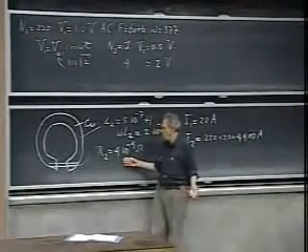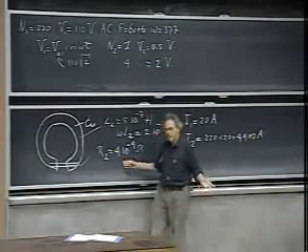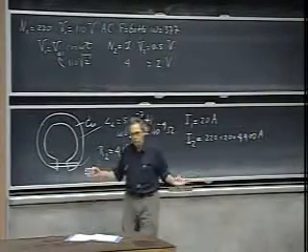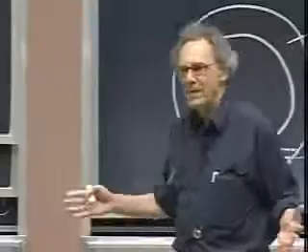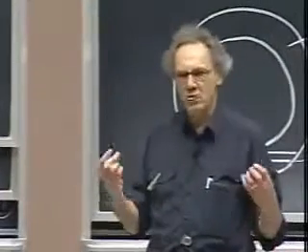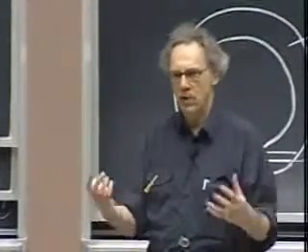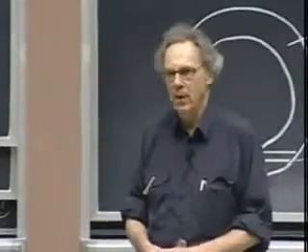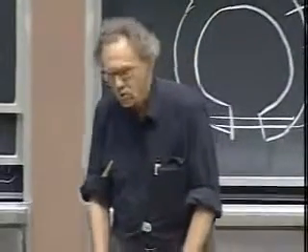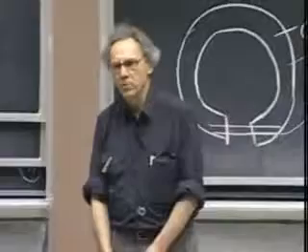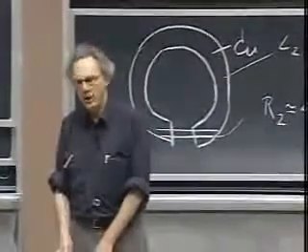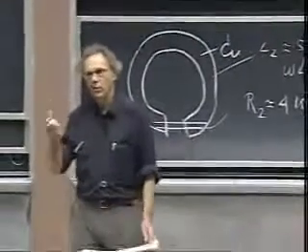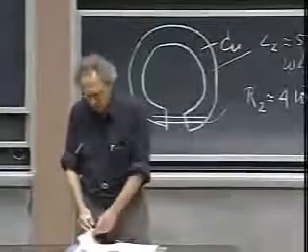And if my current, I2, becomes 500 to 1,000 amperes, you can calculate what I squared R2 is. Because you know R2, that's all in that nail. And that comes out to be about 100 to 400 watts. You better believe it that that nail is going to be red hot, is going to glow, and probably melt. And this is the idea behind so-called induction ovens. This is purposely done to get a very high temperature, it's also done in welding to get very high currents.